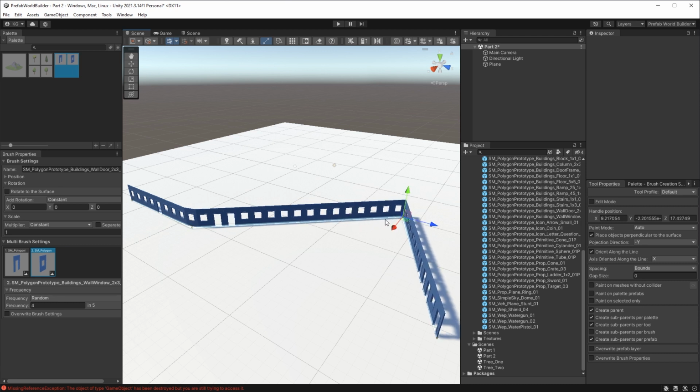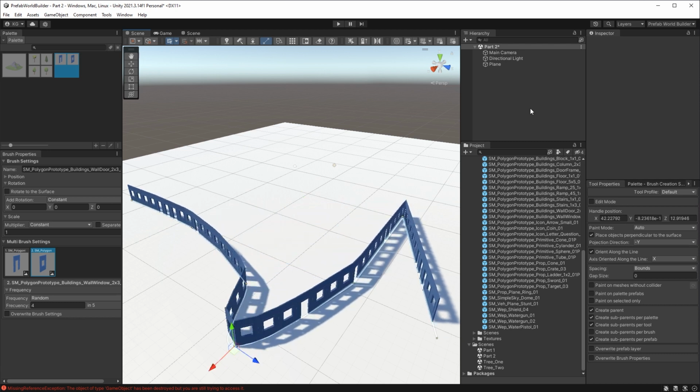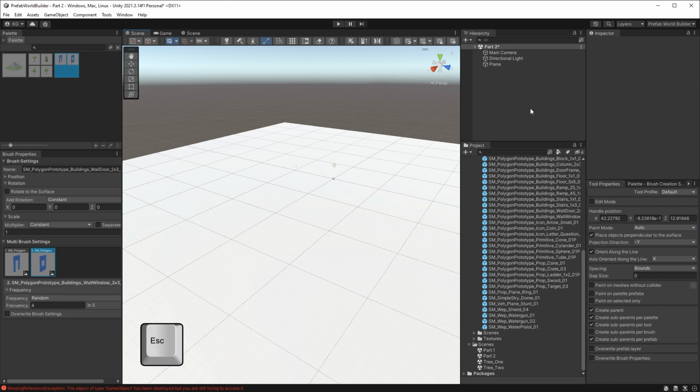If at any point you need more vertices, you can see this faint vertex between the two others. If you click that, it will create another vertex. And you can keep on subdividing as much as you need. Let's press Escape to not finalize this.